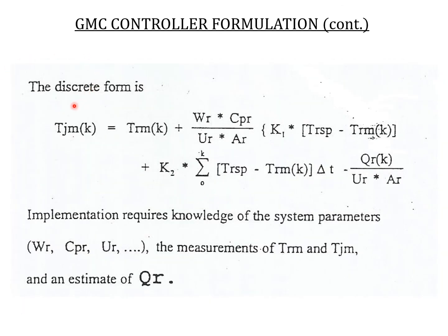And we transfer it into discrete form, because a real computer implementation has to be discretized, so it is discrete time in terms of k, at sampling time k. The integration becomes a summation. The tuning we get from the graph just now, as I told you, and we just implement it in discrete form, because it is normally implemented in the computer, which is automatically in discrete form anyway. But here we can see the discrete form implementation much more clearly for this sort of advanced control method.